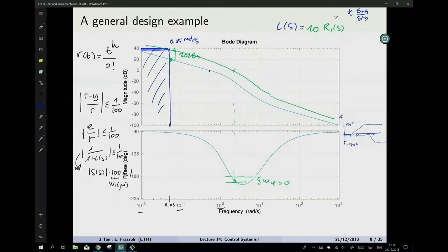Suggestions? Say it again? Yes. So we had agreed that in order to meet the specifications on the margin of phase, which our boss requires to be more than 40 degrees, and now we have a margin of phase that is actually less than 0. We have a negative margin of phase of, what is this, maybe minus 10 or something like that. Definitely ugly, right? We have to bring it up by, let's say, 40 degrees, 45 degrees.